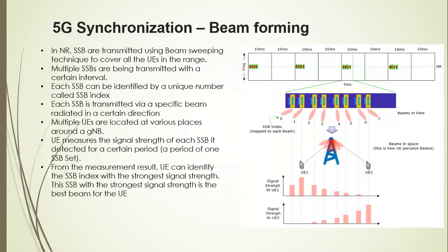Even in MIMO in LTE, beamforming in connected mode has already been used. Dynamically, beams will be formed and informed to the UE, or beams will be chosen based on signal strength. The same thing is applicable here, but here it is applicable even at the time of transmitting the common information and synchronization also.